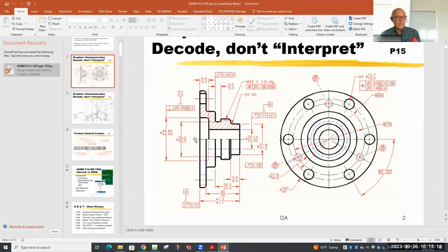If you think of the Cartesian coordinate system, there are 3 axes, and around each axis, there are 3 possible revolutions. Those are your 6 degrees of freedom. One's called translation, you moving along an x-axis, moving along a y-axis, moving along a z-axis. The other one is called rotation. You can rotate this around each of those axes, and controlling all 6 of those means that you put this in a position where it can't move at all. Now you can measure it accurately. Make sense?